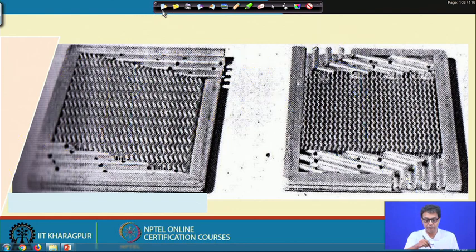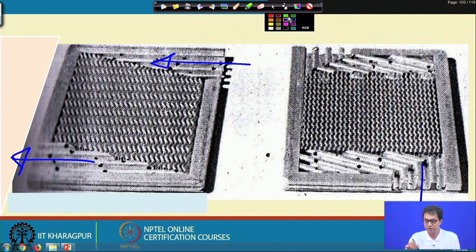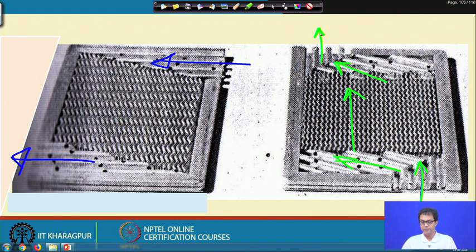But instead, if one fluid is flowing in this direction and moving out in this direction, and we allow another fluid to enter from this end, let it go like this, and then it comes out here, getting distributed over here and moving out. Now if we superimpose one over the other, we will find that it constitutes a kind of counter current plate fin type heat exchanger.